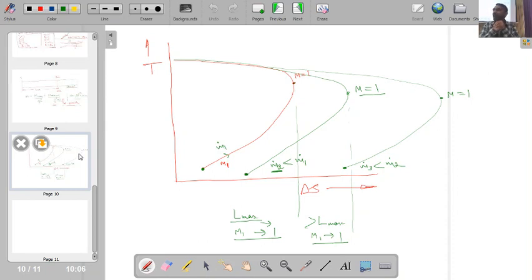And the location at which the shock wave will form depends upon the exit pressure of the pipe and how much additional length there is beyond Mach number equal to 1. So basically the back pressure at the exit of the pipe governs the formation of the shock wave.